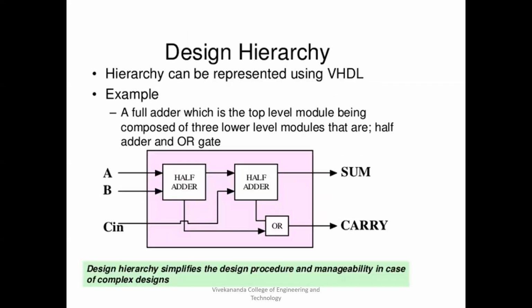Next is design hierarchy, that is in the same abstraction level, either in the behavioral or in the RT level or in the gate level, the modules are broken down into sub modules and then designed. Like if we know we have to use a full adder, either you write an equation and from the equation you take a gate, for the gate you design a transistor, or the other way is that you use two half adders and start designing.